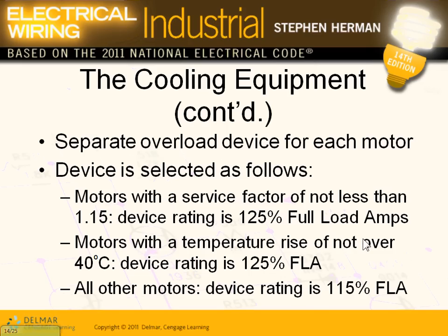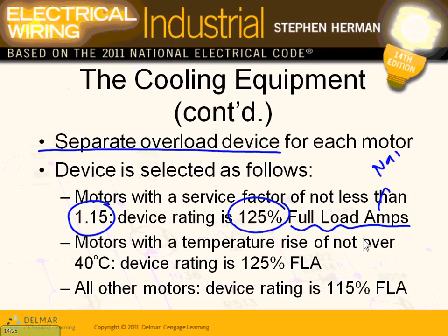Overload. You have done this overload with Chad. Same thing. If you are very familiar with this, the overload can go from this value to this value multiplied by the full load amps on the nameplate. So this is a review of what we have done, the nameplate. If you have no idea what type of equipment you have, what do you start with? Most conservative, you go 115. When do you use 115 and when do you use 125 for motors? You remember that rule?